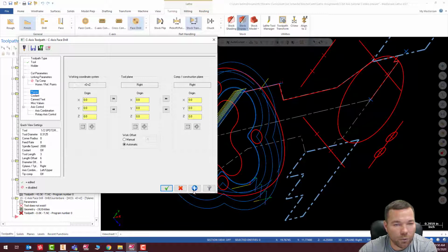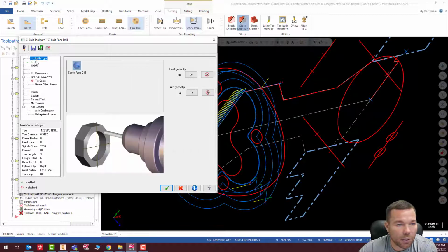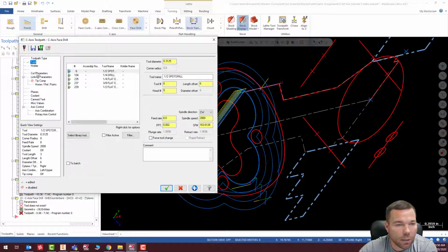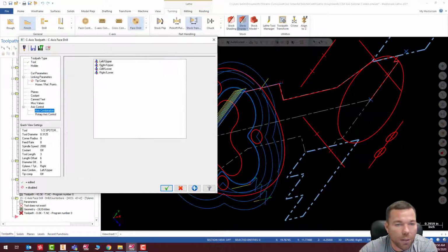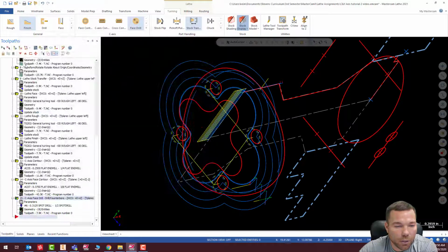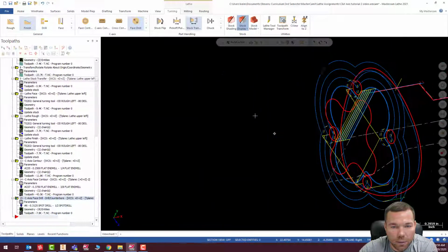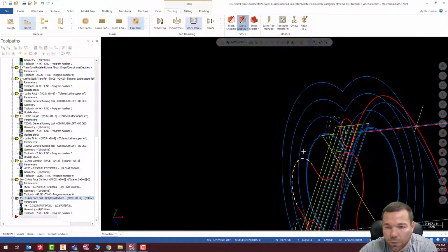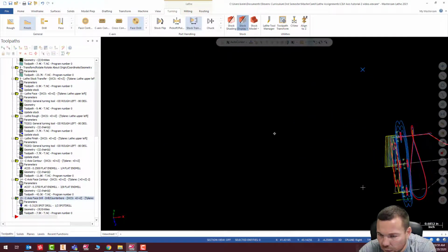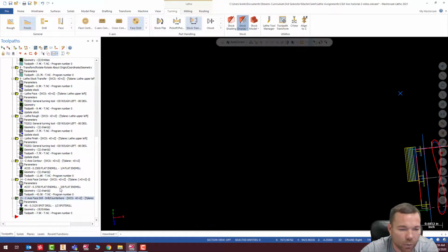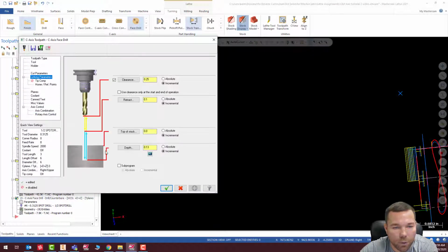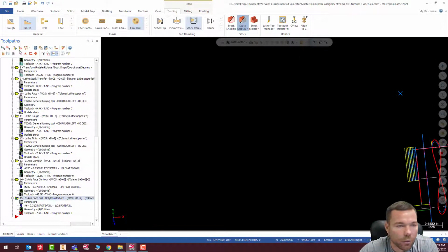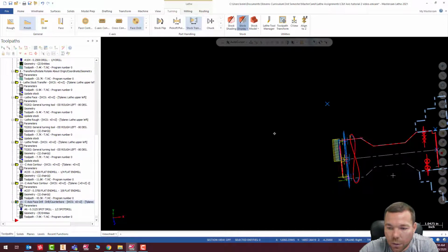Everything here looks good. The only thing I need to change is my axis combination. Where's my axis combination at? Oh, it's down here. Upper right, check. And you can see right there I have my holes being drilled. And it looks like, if I'm not mistaken, I put a bad number in. Looks like I put a positive in for my linking parameters. I sure did. Negative, check. And let's regen that. All right, that looks a little better.